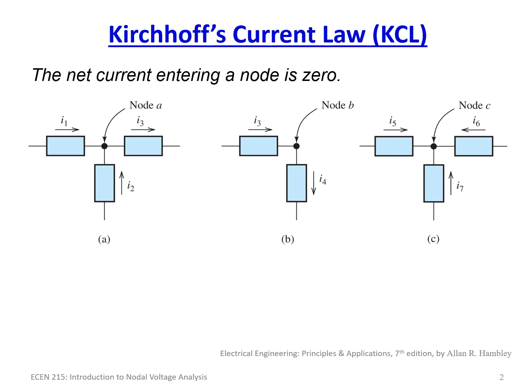So it's just important that you understand, again, the purpose of the arrow, and it also, when we talk about circuit elements where we assign pluses and minuses, that for an absorbing circuit, again, if the current is flowing from the positive to the negative, it's absorbing. So we have 5 amps flowing through it in this direction. Then we would expect to have a voltage drop of, say, 5 volts across this. And using Ohm's law, if this was a resistor, say, and we had 5 volts across this element and 5 amps, then correspondingly the resistance would be equal to 5 volts divided by 5 amps, which would be equal to 1 ohm. So just to make sure you understand the principles here, because we're going to be building upon this.